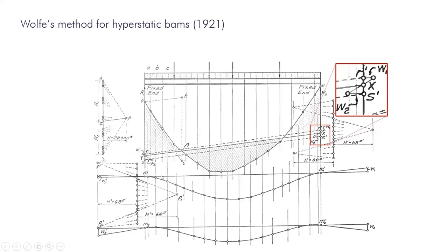And you see that at the end, the direction of the last line gives you an angle. It should be horizontal since you have embedded ends, but here you have a result. So it gives you an angle at the end. So that's not the proper solution. We'll try with another polygon here below and do exactly the same. And you have here the deformation built as a funicular polygon, and you have this time a deformation in the other sense. The true solution is in between, somewhere else.